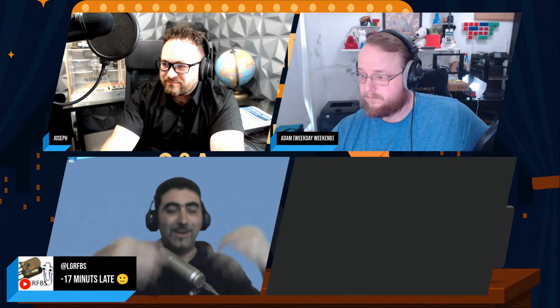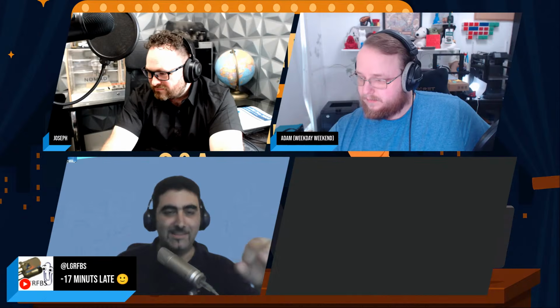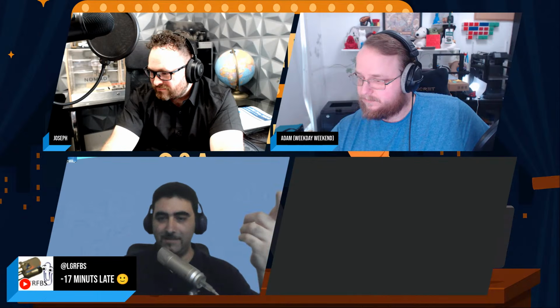You take the nominal, you subtract the pitch, and you get your pre-drill diameter. Whereas the TPI one is easier for the engineer to calculate if the fastener can take the load, the preload you want to apply. Because for the preload, you need to calculate how many threads are in engagement, and the effective diameter of your bolt. So inch is easier to calculate loads. Metric is easier to manufacture. There's an interesting tidbit for you.